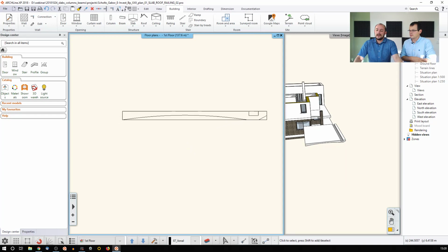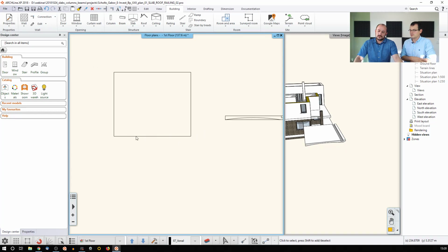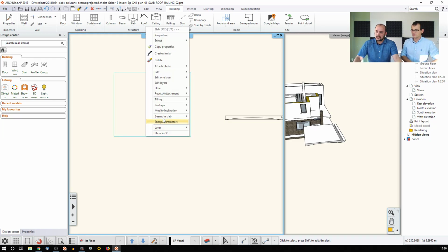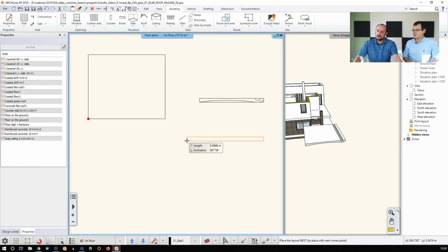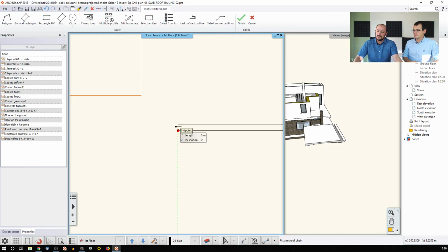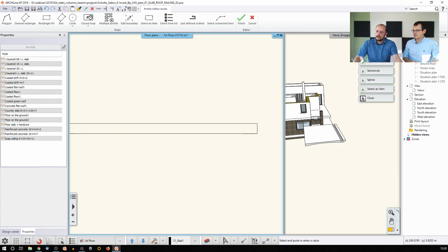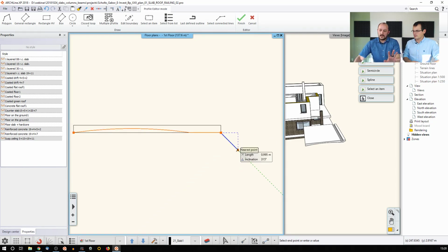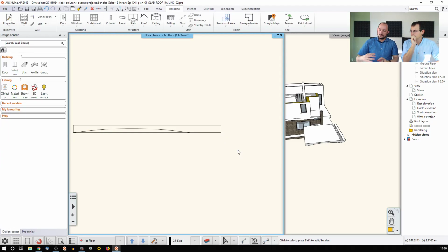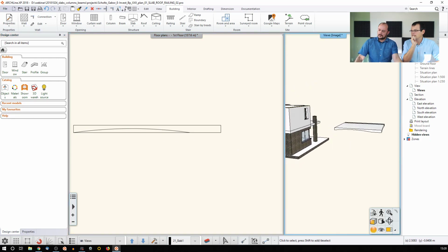Now, if I do the other option the other way around, this is what I get. It's the reshape, and I add bottom profile. It looks the same. I have the same layout, and I actually just simply click here and again say arc. There's an arc here, and I'm done. I actually cannot create the top now because it's only the bottom profile. So if you know that what you look for is only the bottom, then this is what you will go with. And this is how it looks.